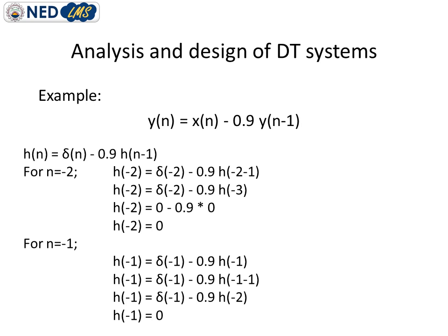You can notice that in the difference equation we have feedback associated with this equation, which means that this filter is an infinite impulse response filter, and we can also say that this system has some feedback. You can also notice that we have a negative sign with the coefficient, so it will obviously affect the impulse response of the system.